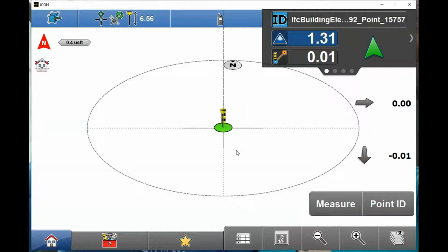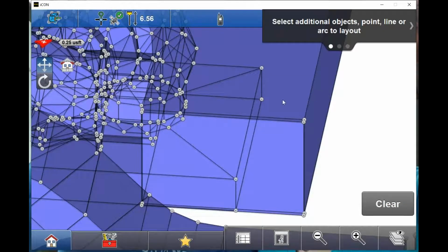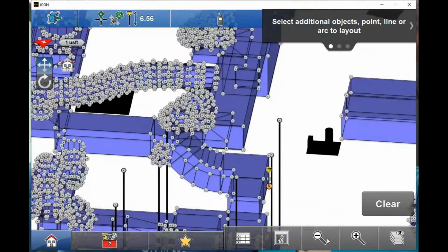And then also with a robotic or manual total station with reflectorless, have it shoot the laser pointer out the front, make your mark that way. Then when I'm ready to select my next element to stake out, after I mark this one, I just click on the screen, and now I'm back live to select the next element. And I would just pick and go that way. A ton of different tools.